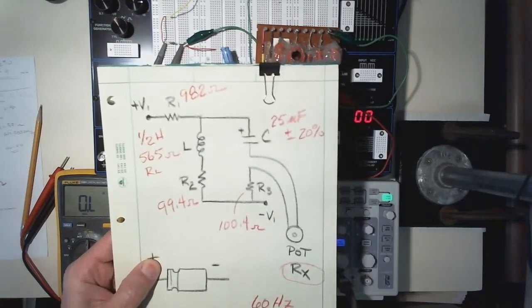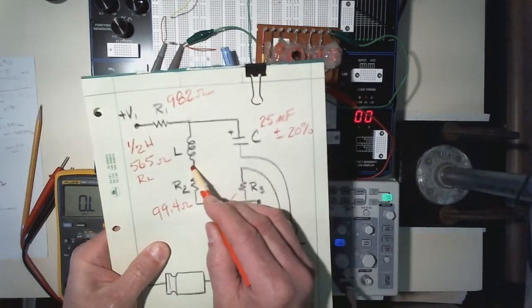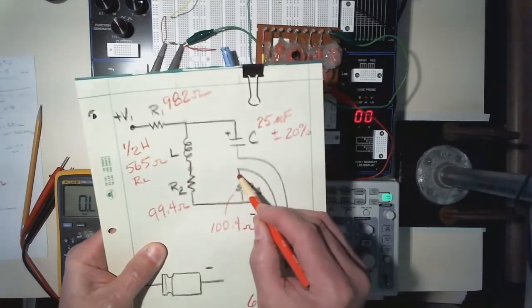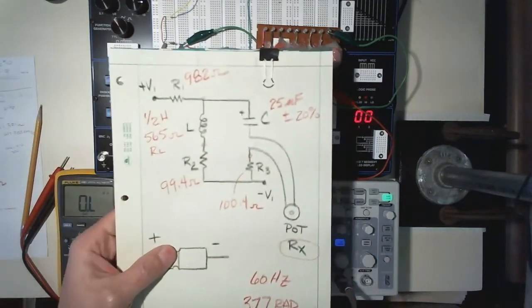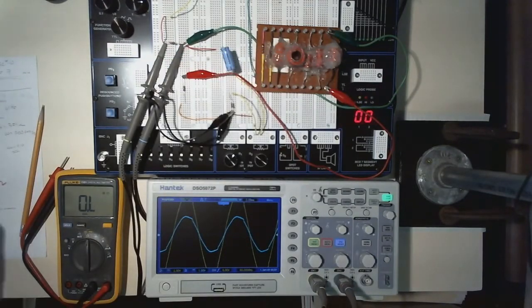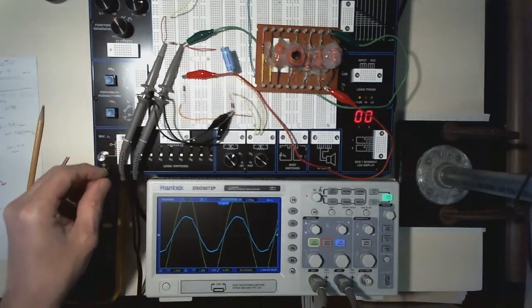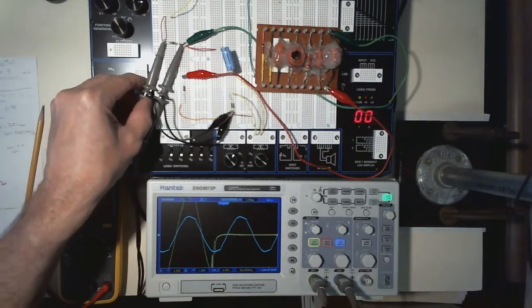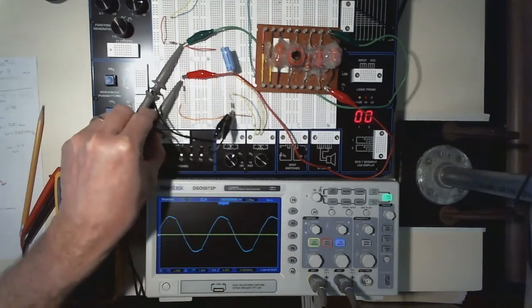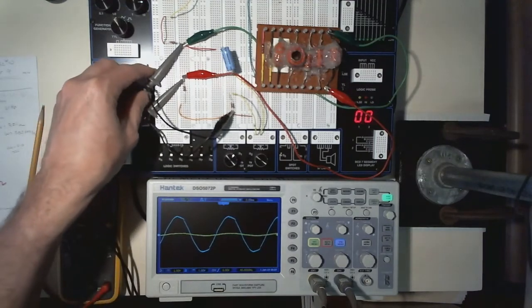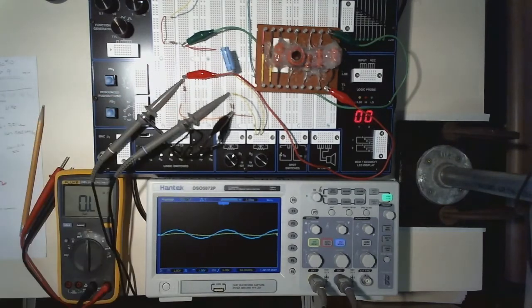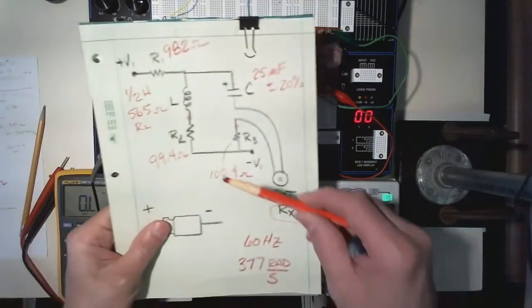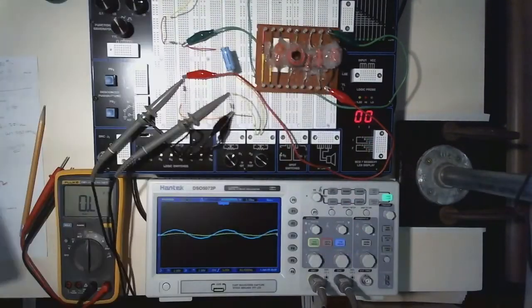One of the steps in the procedure, if you've looked at it, says to put a probe right here and also a probe right there, at points 3 and 4 if we go back to the original schematic. So let's do that. Before I move these, they are definitely in phase. Let me move them. I'm going to put channel 1 over here, and then I'm going to put channel 2 right there. So I've got channel 1 right here, channel 2 right there.